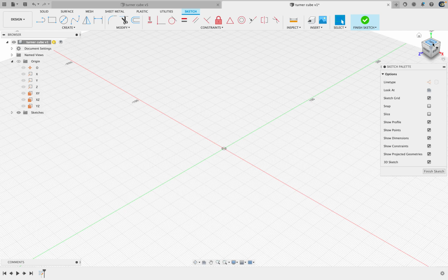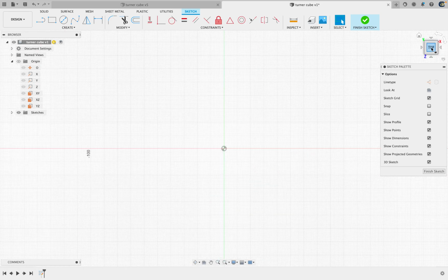I will click the top-down view. I'm going to right-click on my view cube to start off with and make sure that I have perspective with ortho faces. That's my preferred view. I would really caution you to make sure that you don't have just plain orthographic turned on. Some people can really understand things in orthographic, but I've found that most people cannot.